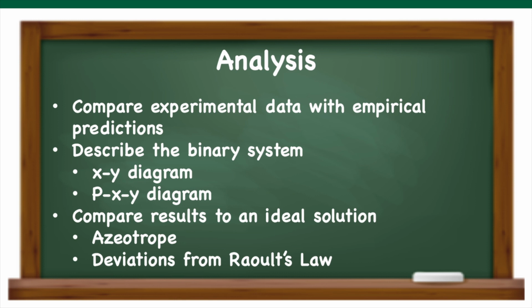Based upon the data collected in this experiment, you should be able to compare the experimental data with empirical predictions using the Van Laar activity coefficient, describe the phase equilibrium of the ethanol water system via XY and PXY diagrams, and compare this system to an ideal solution by evaluating the existence of an azeotrope and deviations from Raoult's law.